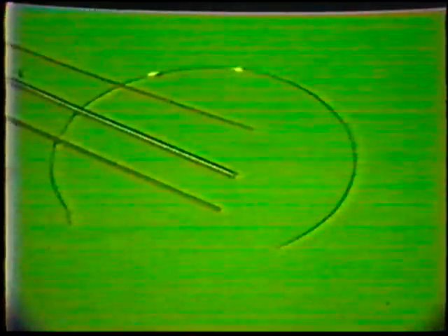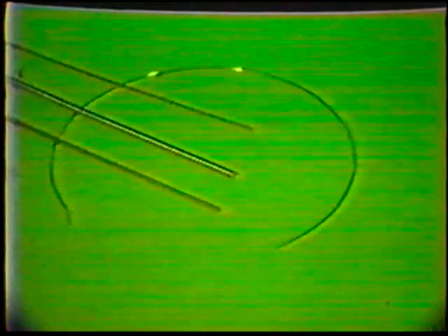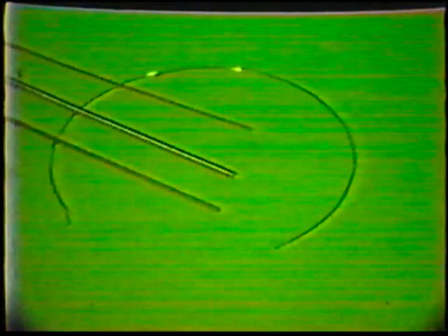The filler metals used with this process also differ with the application. For fusion welding, filler metal is supplied in compositions that match the material being welded. Sizes range from 1/16 to 7/16 inch in diameter and are usually 36 inches long.